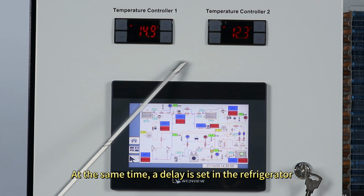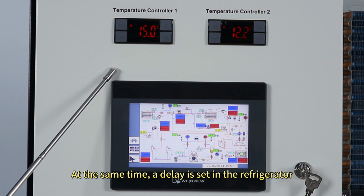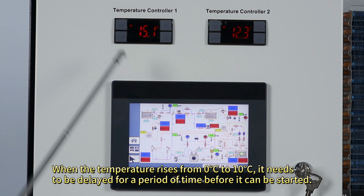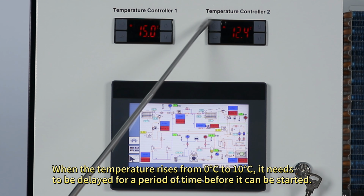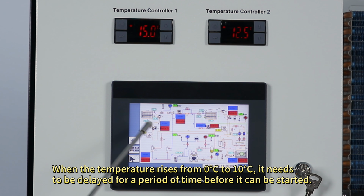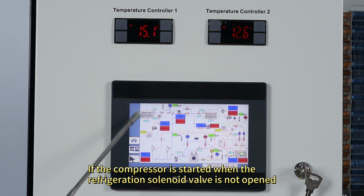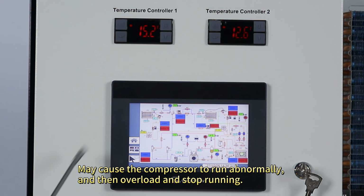At the same time, a delay is set in the refrigerator. When the temperature rises from 0 degrees centigrade to 10 degrees centigrade, it needs to be delayed for a period of time before it can be started. Do not click the compressor start button at this time. If the compressor is started when the refrigeration solenoid valve is not opened, it may cause the compressor to run abnormally, and then overload and stop running.